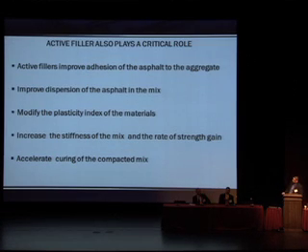Your active filler, in our case it was cement. You could use lime, fly ash, and a number of other products. We had cement on the job, so it wasn't an issue. Active fillers improve the adhesion of the asphalt to the aggregate, improve the dispersion of the asphalt in the mix, modify the plasticity index of the materials, and increase the stiffness of the mix and the rate of strength gain, and accelerate the curing of the compacted mix.